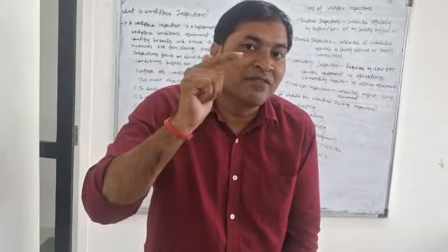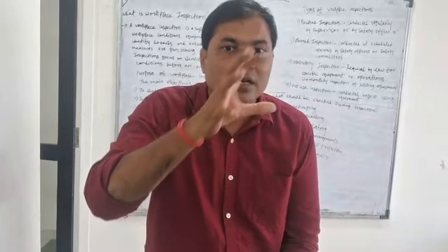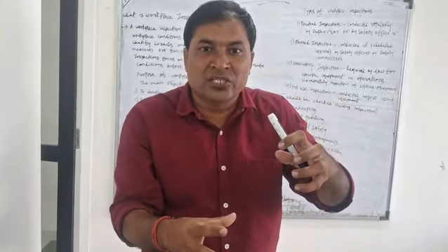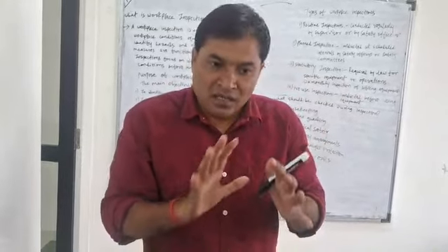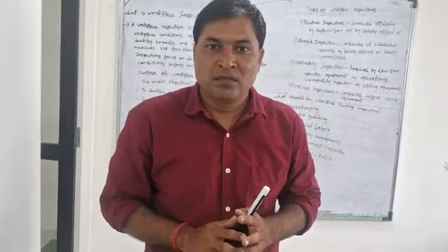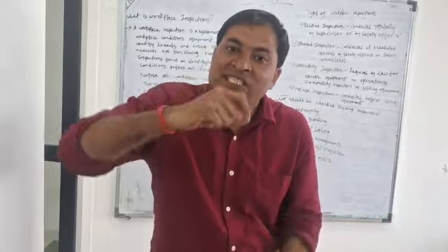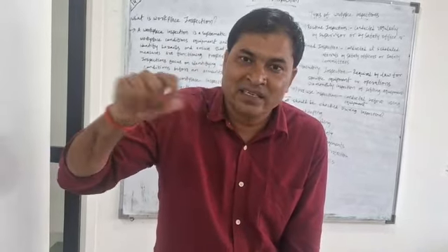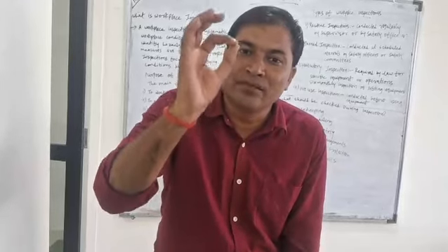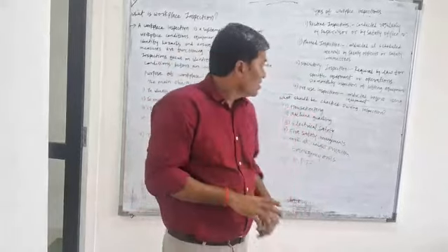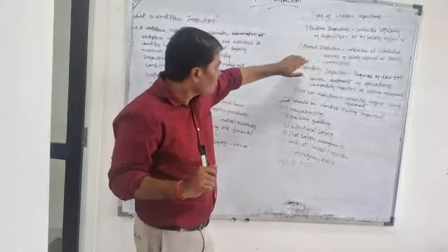If you are checking extinguishers, check the pin, clip, pressure gauge, and the whole body, whether it is properly painted or not. So go with the checklist, check every point and tick it. Thorough inspection is very important. Understood? That is routine inspection, which you have to do every day.